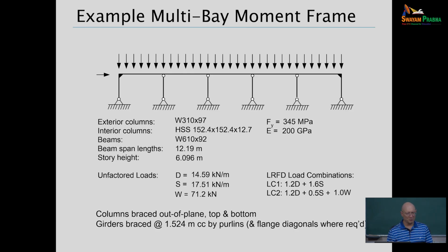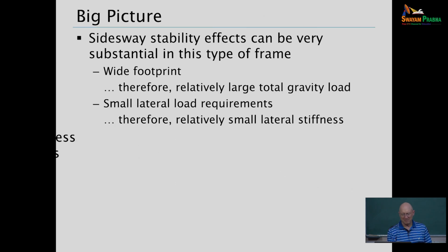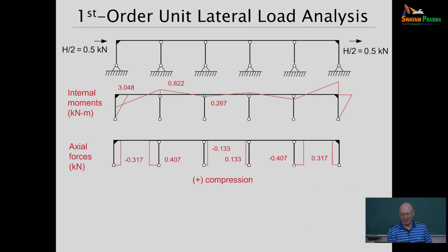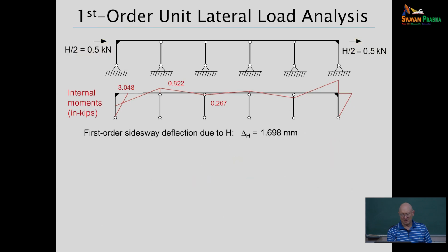But here's where things are very different in the Americas. We would say, on this frame, if I'm going to do direct analysis method, I'm going to analyze everything with 0.8 of the nominal elastic stiffness. That's a very rough attempt to approximate that I'm going to lose some stiffness from yielding, etc., as we're approaching strength conditions. Okay? So all these analyses are being done that way.